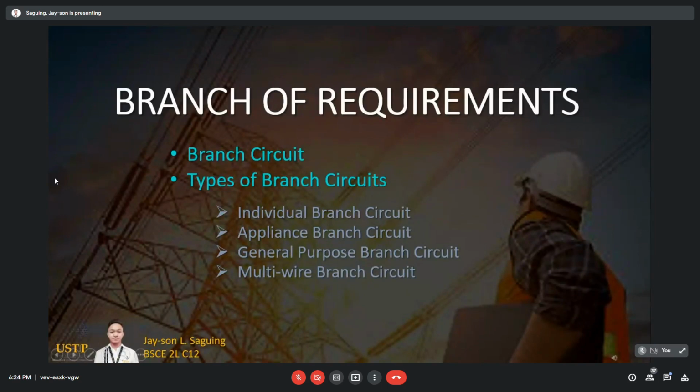Your home's electrical system begins with main service wires that enter your home from an overhead utility line or underground feeder wires and connect to the main service panel, usually located in a utility space or garage. Many smaller homes may not have the option of a utility space or garage, in which case the main service panel may be located on any accessible outside wall. It may also be located outside, but only if it's a weatherproof panel type.